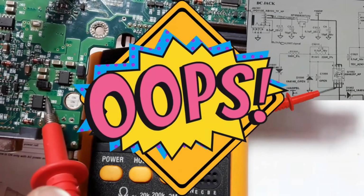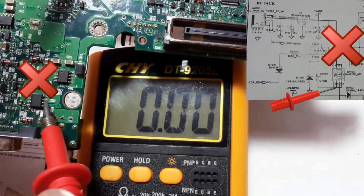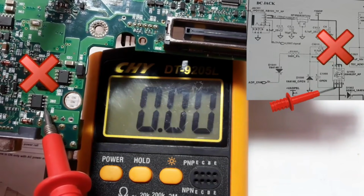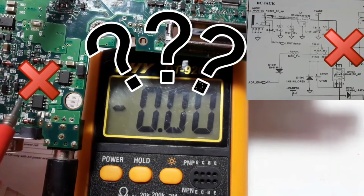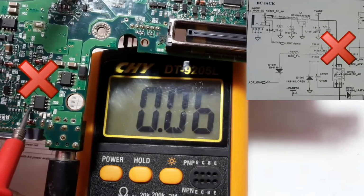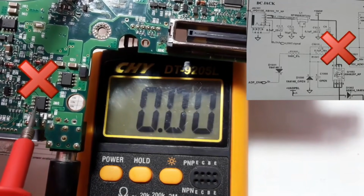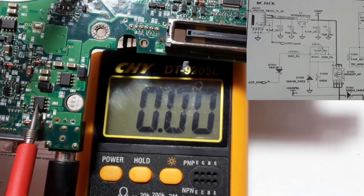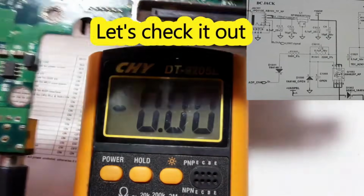Oops. We have 0 volts. Means here we have the problem. This MOSFET is failed or we have a short circuit in this motherboard. We have two options. Maybe this MOSFET is failed or we have a short circuit on the other side of the MOSFET. So let's check it.